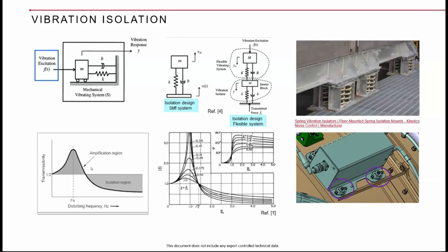Where it is possible, especially for components such as blocks, manifolds, or electronic systems, which we anticipate that the vibration should not disturb the functionality of the electronic boxes, especially FADEC, and you have a lot of control systems on the engines. FADEC is Full Authority Digital Engine Control. Okay, so such systems, aircraft electronic controls, AECs on the wings, and you will have several such control systems that need to be isolated from the excitations.